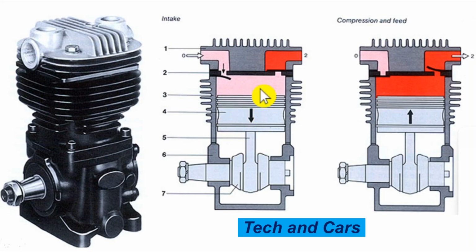And the other thing that can cause oil to mix in here is oil overheating. Too much oil in the compressor will lead to it being forced out. So those are some of the things that can cause oil to mix with the compressed air, and that is also a sign of trouble.